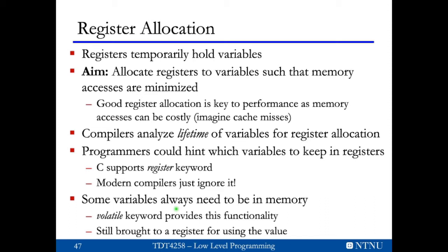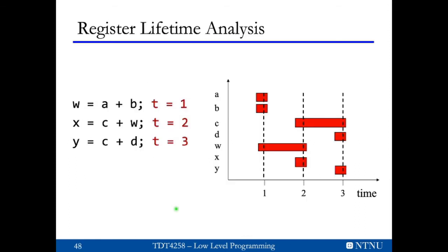So volatile is especially important when writing device drivers, implementing semaphores in memory. So any condition where something might happen that your compiler can't know about, like hardware functionality or a parallel process that's executing and using the same shared memory region for doing synchronization.